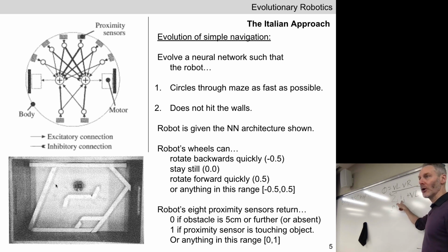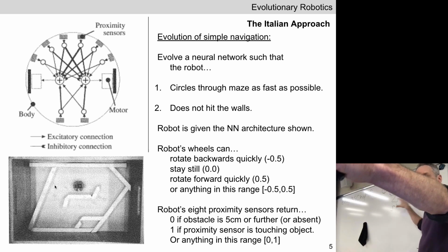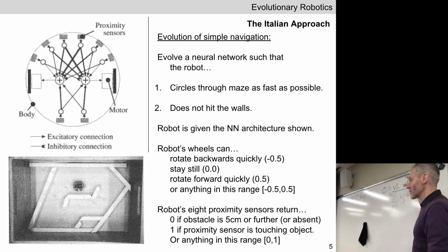As it starts to drive forward, what's happening to the 6 proximity sensors on the front of the robot? Maybe not all 8, but for the majority of the 8 proximity sensors, what's happening as it starts to move forward? The values are changing. The values of the 6 on the front changing how? Well, we're getting closer to a wall, so they're going to have higher values. They're going to start to increase. So the value down here on the denominator is starting to increase, which is pulling the whole value of phi downward, which is good. That's the intuition that we want.